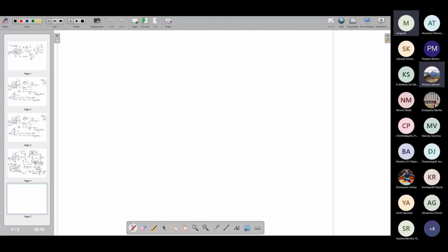And then when we discuss some feedback concepts, we will see how this circuit can be useful for interesting feedback circuits where you can get a high performance as well as low input impedance. Impedance requirement in many circuits, especially with a transimpedance amplifier, may be very low. You may require an R in of 100 ohm or 50 ohm. So how to get this R in of 50 ohm also happens to be a challenge, and we will look into that. We will see, using special feedback techniques, how we can get a very low input impedance.